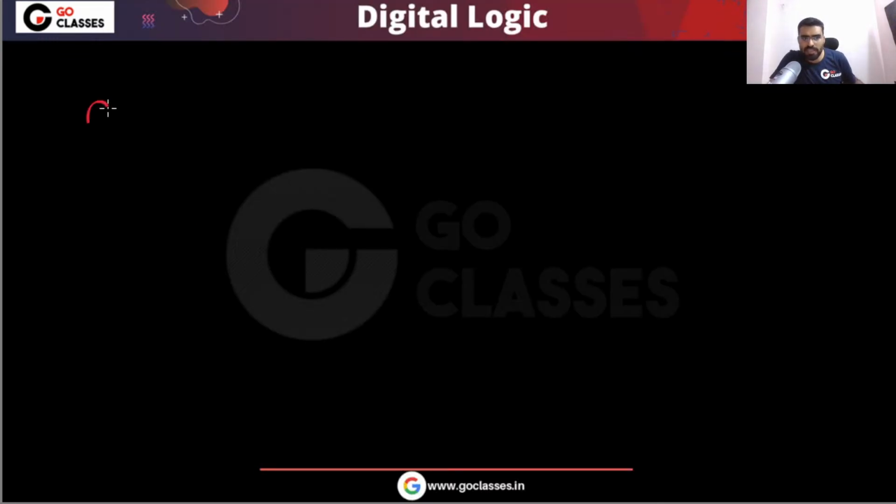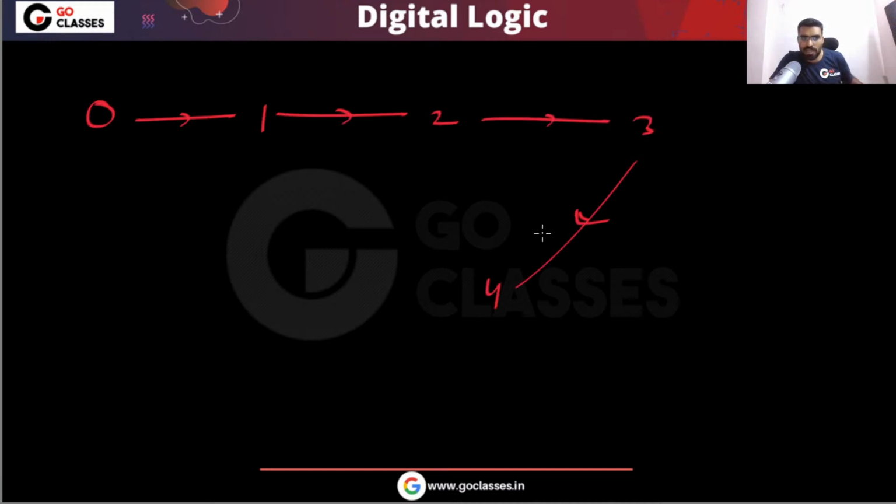So your counting is like this. From 0 you are going to 1, then 2, then 3, then 4. Then for a moment, actually, you are going to 0. For a moment there will be 5, and immediately it will become 0. So I can say this is a mode 5 counter.